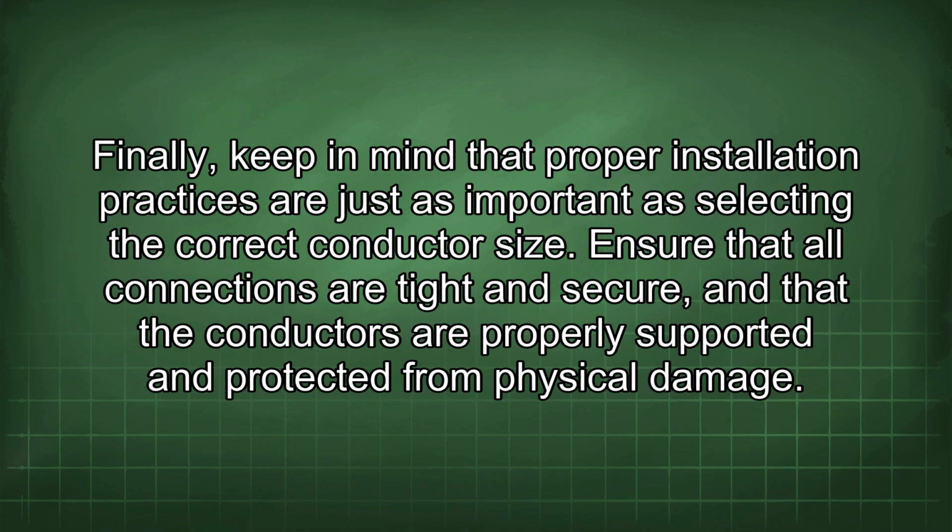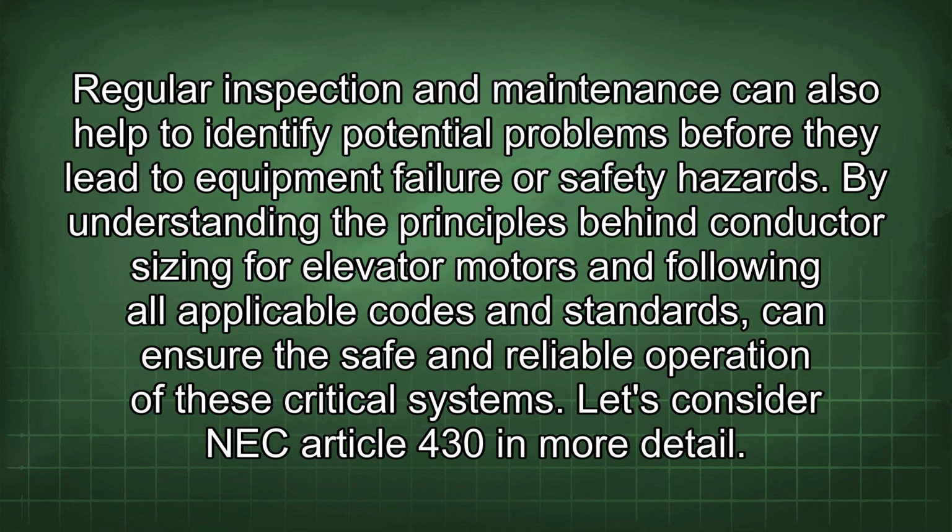Finally, keep in mind that proper installation practices are just as important as selecting the correct conductor size. Ensure that all connections are tight and secure, and that the conductors are properly supported and protected from physical damage. Regular inspection and maintenance can also help to identify potential problems before they lead to equipment failure or safety hazards. Understanding the principles behind conductor sizing for elevator motors and following all applicable codes and standards can ensure the safe and reliable operation of these critical systems. Let's consider NEC Article 430 in more detail.